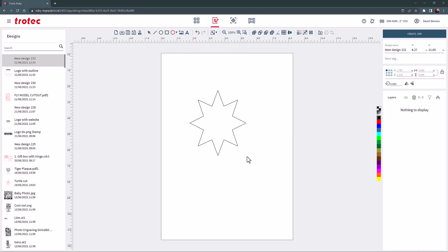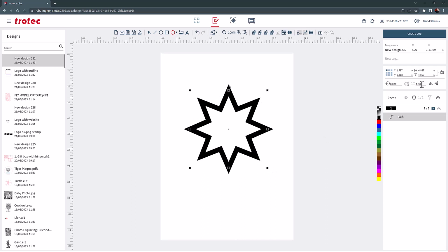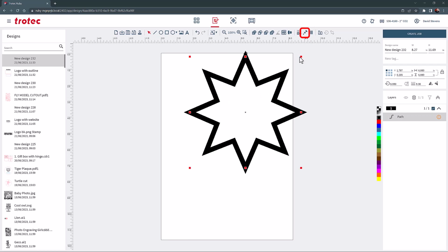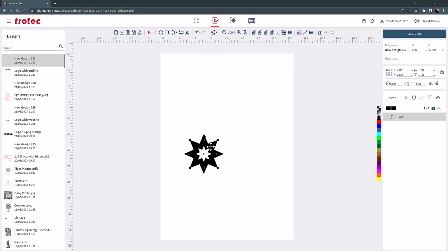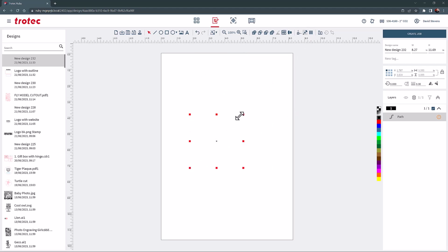When engraving a design element like this star using thick line weights, the outline scaling tool may be necessary. This will allow the design element to maintain the same look as it is scaled up and down. Without this tool, the design's line will not change, producing a thick line when scaled down.